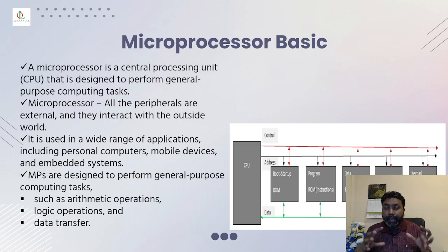So that adds a lot to the cost, because you need to design each and every individual module, and you can communicate that via the control, address and data bus. It is advantageous because you can keep on extending if you want to have further peripherals added, which is a really good point. So the microprocessors are designed to perform general purpose computing tasks, which has all the arithmetic operations, logic operations, and data transfers.